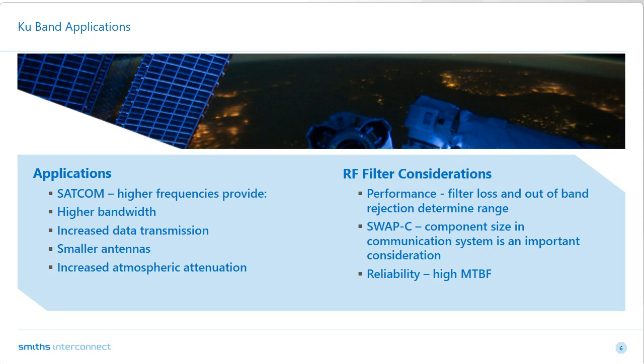One of the challenges is with the atmospheric attenuation of signals due to rain, sleet, or snow, also known as rain fade. The attenuation of electromagnetic energy due to water vapor does increase with higher frequencies, and there are some wavelengths that have significantly high attenuation. This is one of the reasons why the K-band was segregated into the Ku, or K under, and the Ka, or K above bands, as the center of the K-band has very strong attenuation from 18 to 27 gigahertz. Rain fade is also a factor for frequencies above around 10 gigahertz.